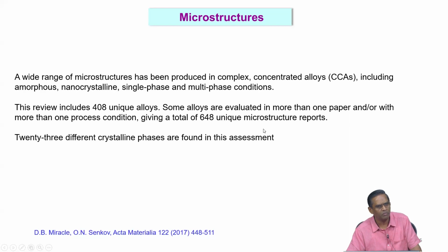When you say unique microstructure, what do you mean? Grains and grain boundaries and different phases. Could be a single phase, two phase. It can have defects, or it can have a second phase. All of them. So when you say unique microstructure, that means each microstructure will have a very specific fraction, phases, defects, second phases, and so on.